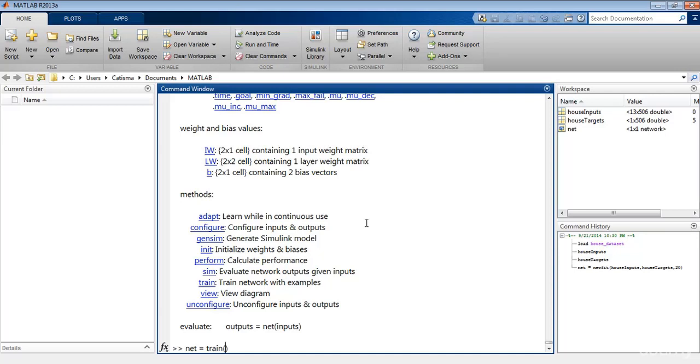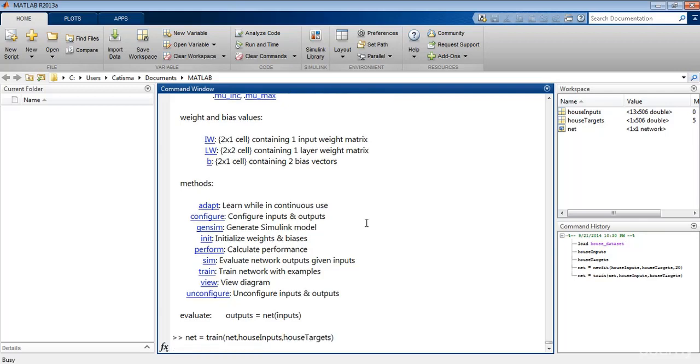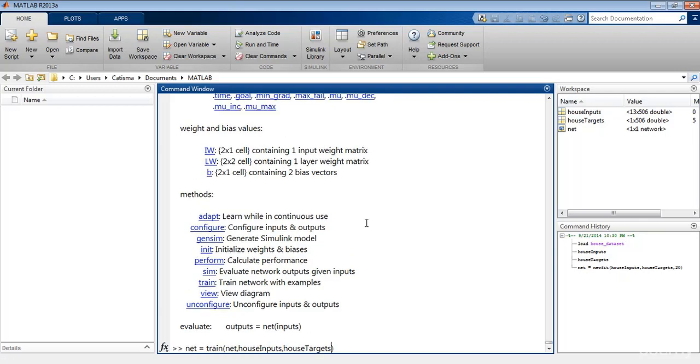This function trains the network according to the input and output data using Levenberg Marquardt as its default, and splitting a dataset into three categories: 60% randomly chosen for training, 20% randomly chosen for testing, and 20% chosen independently for evaluating of the network.